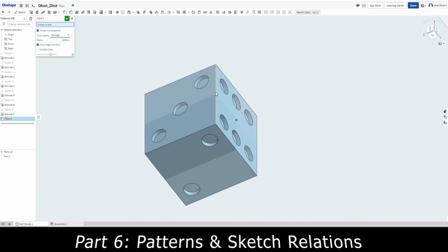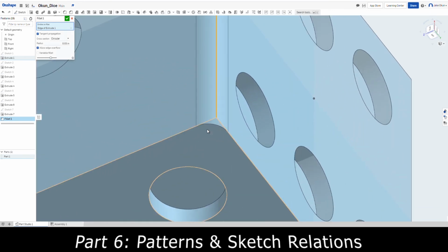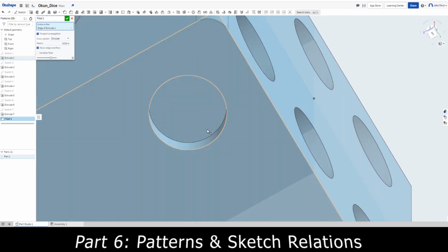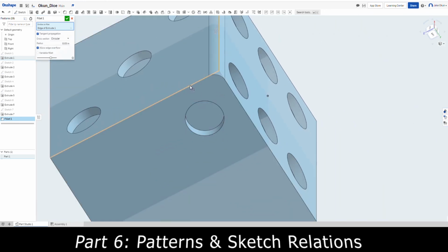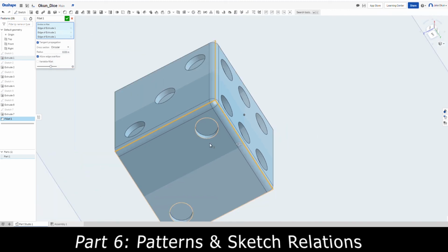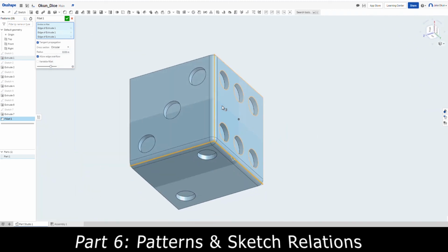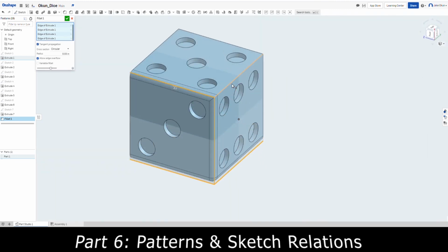And then all we're going to do is select the edges. So there's one edge and you'll notice that it'll change automatically. So just to show you before I change any other ones, you'll notice how it looks just like a circle on the one side with a radius of 0.03 inches. Now we're just going to do that on every other side. So just select and you'll notice that it'll create a nice even line and it'll automatically do this for us, which is really nice. So just like this, now it's rounded corners. So that's one corner and intersection of this die. Now I'm just going to do the rest of them. So select, select.